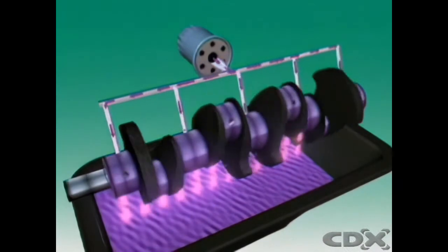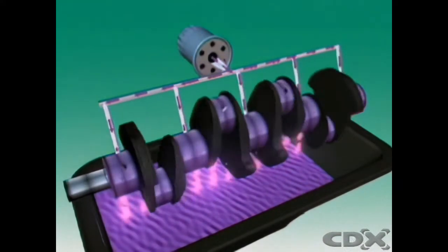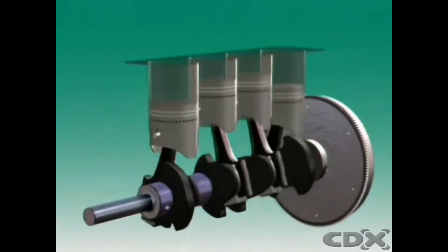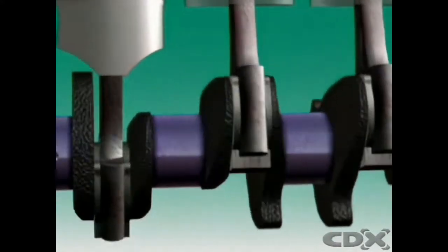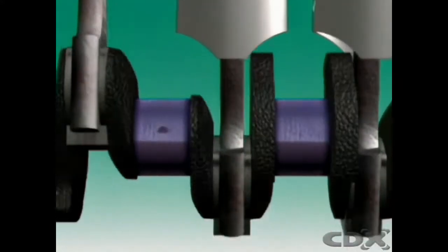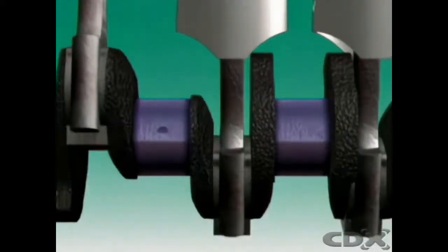It helps cool an engine. It collects heat from the engine, then returns it to the sump where it is cooled. It helps absorb shock loads. A power stroke can suddenly put as much as 2 tons force on main bearings. Layers of oil cushion this loading. Oil is also a cleaning agent. It collects particles of metal and carbon and carries them back to the sump. Larger pieces fall to the bottom.